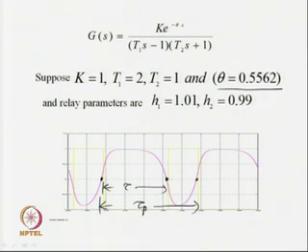What we observe from here, interestingly, is that τ increases when the value of θ, the time delay associated with the unstable system, increases. Similarly, τp is also increasing. So, those are increasing gradually. If I further increase the θ value, definitely τ and τp are going to increase substantially. So, this is one observation we have got.